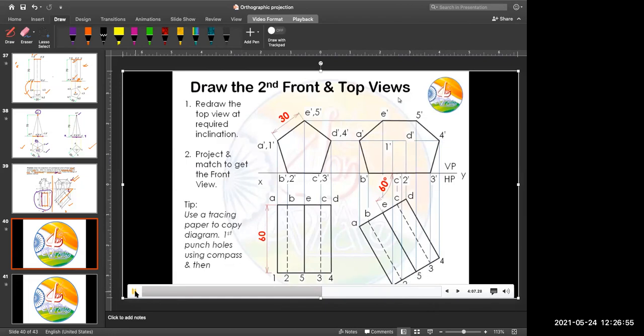Completing the outermost boundary, now we have to view from the opposite side to identify which of the inner edges will be visible. So in this diagram, we see that the point which first comes is point 1. So in the front view, all the edges which are coming from vertex 1 should be visible. All the remaining edges should be hidden, hence have to be drawn as hidden lines.